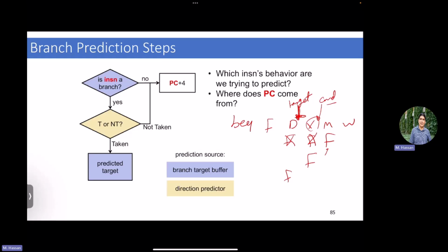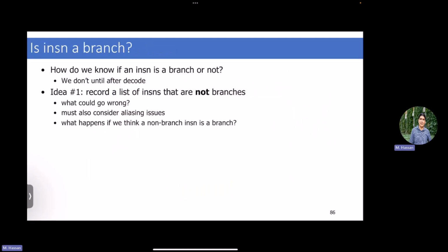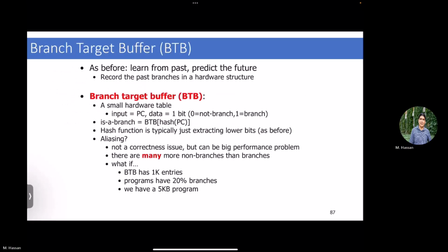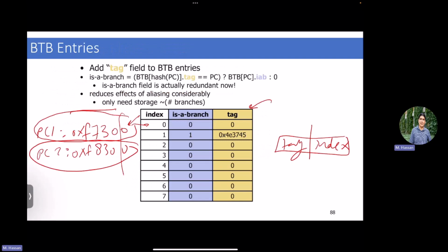And these are the tables that we're going to discuss right now. I'm not going to cover the BTB much because, as I said, it's a simple operation and it has very high accuracy most of the time. The idea is that if you have loops and you stored the program counter before, you are sure it's a branch. If you only store it before, you make a guess and then you correct yourself later on. So it's a prediction, but you are either correct or wrong. There is no need for a lot of history or machinery.